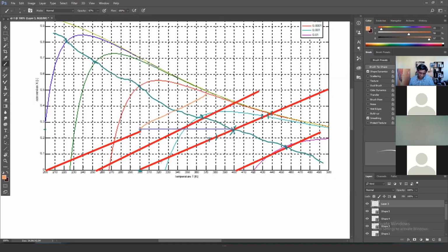In this case, T in was 300. For this red line, T in was close to 250. For this red line, T in was 200. So these are exactly the same concept. These are all adiabatic lines. These are all operating lines in the CSTR. Your reacting fluid, if you start at 200, is going to react up along that line. So whatever your inlet temperature, it's all going to increase with that gradient. Does that answer the question?